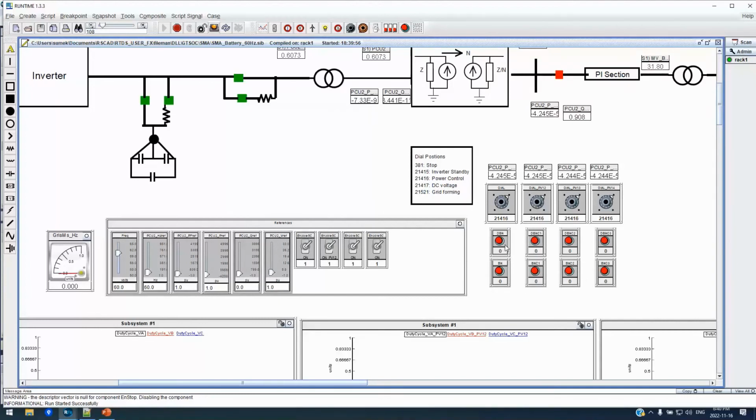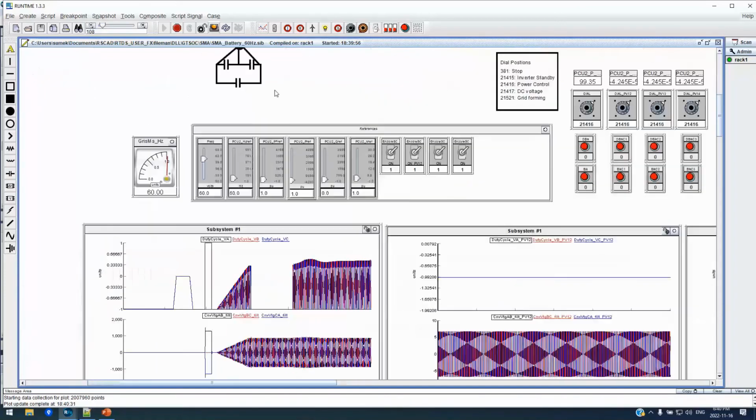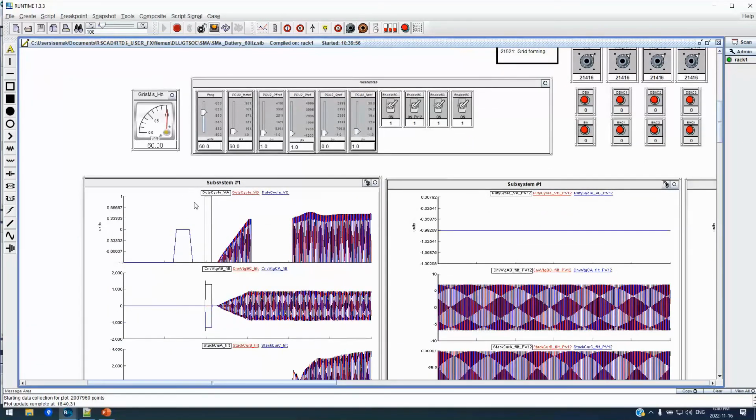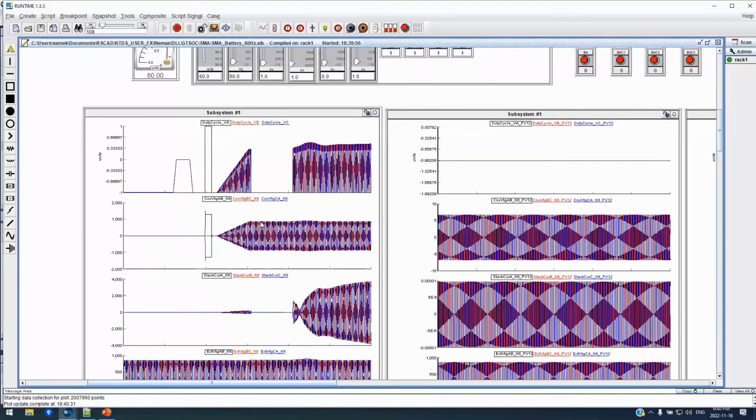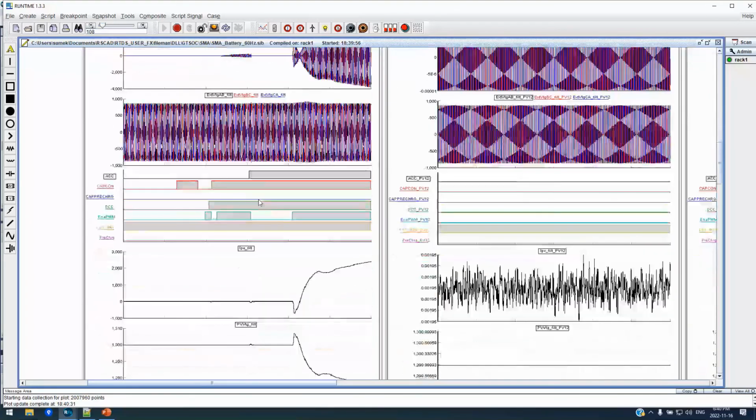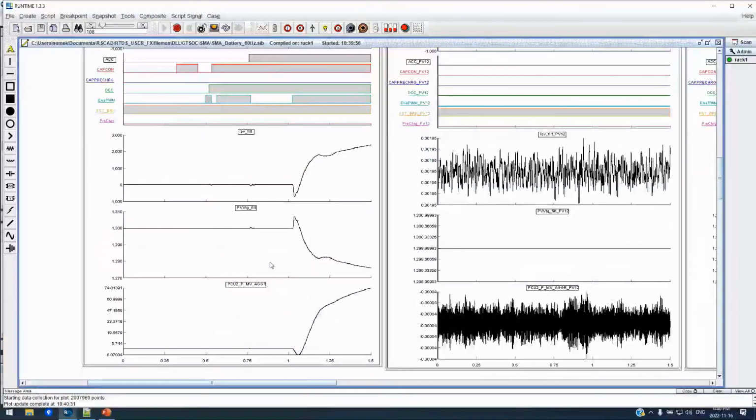So then I will deblock it. You can see here, I now get 3.6 megawatts on the inverter side, and with the scaling I get about 100 megawatts. That corresponds to 1 per unit power, which I have set here. You can see the deblocking transient from the duty cycle and the voltage. Talking with SMA and showing the results, this is exactly what they would have expected.